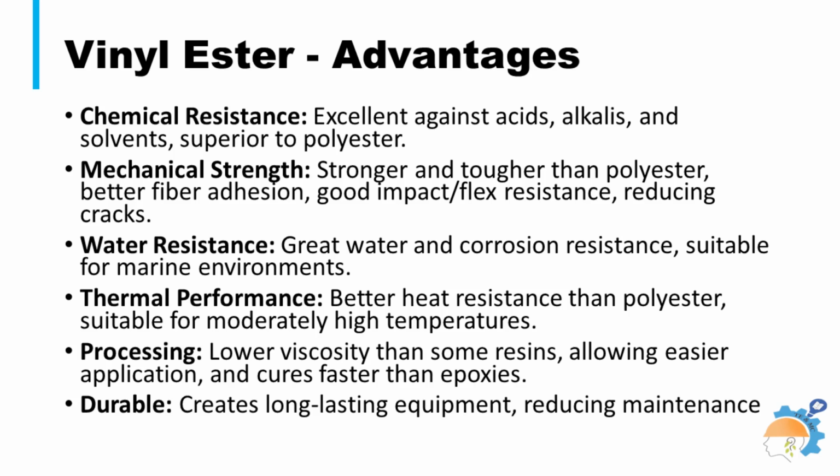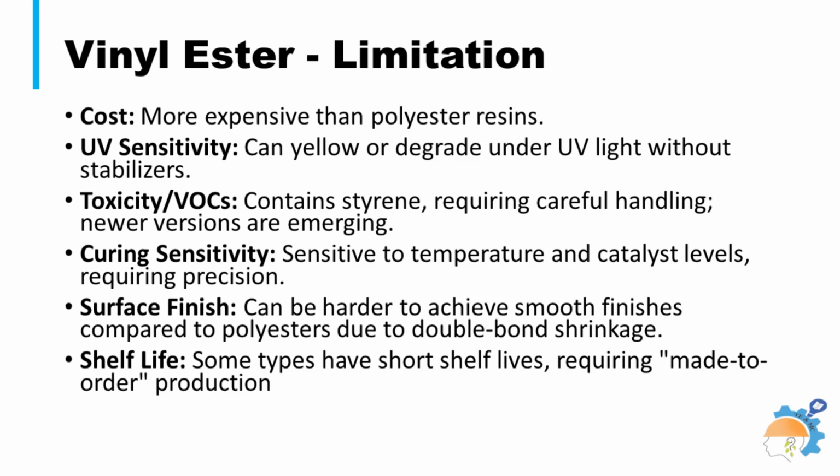Vinyl ester resins offer excellent chemical and corrosion resistance, superior strength and toughness over polyesters, good water and heat resistance, and some flexibility, making them ideal for harsh industrial or marine use. These are pricier, can have short shelf lives, contain toxic styrene, and require precise curing, with less UV resistance. Surface finish of products is not of very high quality.